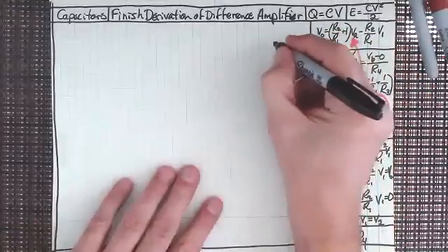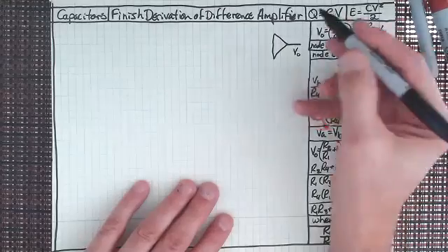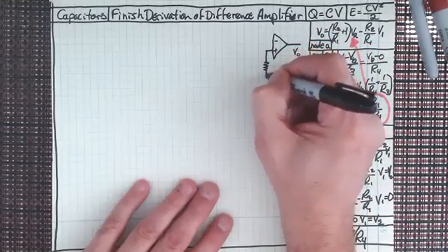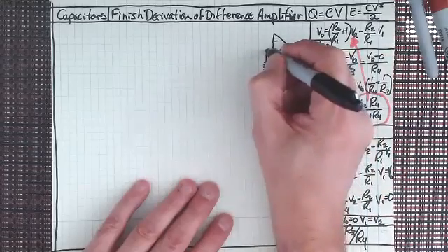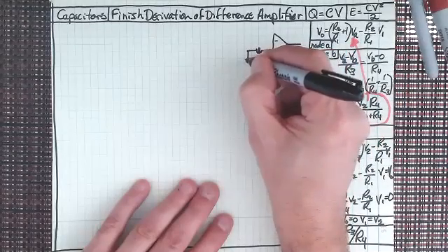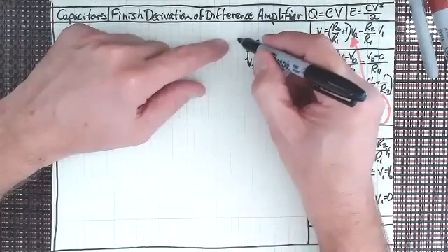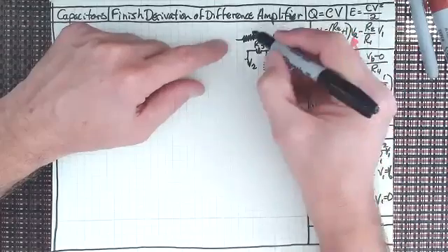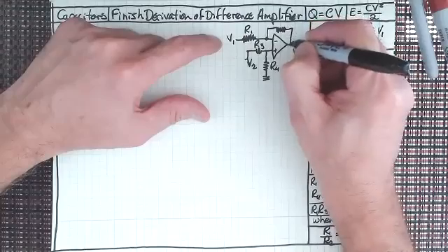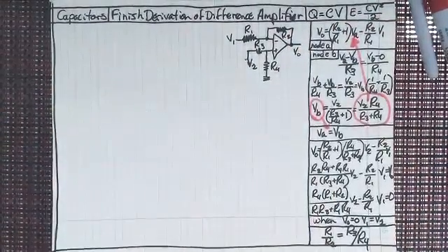And in fact, let me draw that difference amplifier again. V out, right? Positive or non-inverting and inverting inputs. I take this one, I go to ground with it. That's R4. And then I have another resistor here that's going to be hitched up to V2. I'll just say V2. Everybody knows it's a DC voltage that's going to be fed in there, and this is going to be R3. And then I have another input, and this is going to be R1, and this is going to be V1 going in, and I have a feedback resistor on that loop. So we're going to put R2. All right, does everybody see that's the difference amplifier?